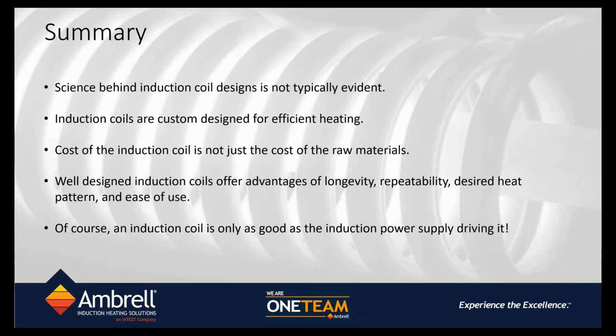All right, thank you, Girish. Our next question is, how many cycles are there before a coil burns up? So an ideally designed induction heating coil should never really burn up. If it has enough water flowing through it and the design is correct, the coil should not burn up.